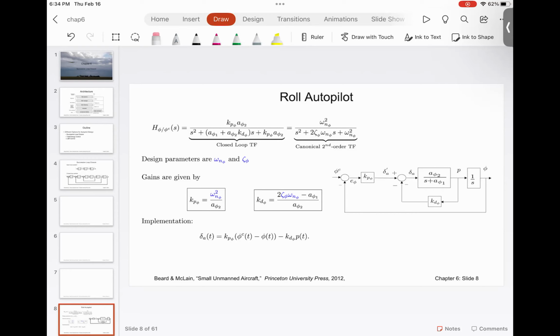If you want to reduce the resistance of the damper, you open this valve and this valve so that the piston can slide easily. If you want to change the resistance of the fluid, just close one valve, open one valve, and so you can tune this damper either intermittently or make gross changes. So that is how the damping coefficient is changed.